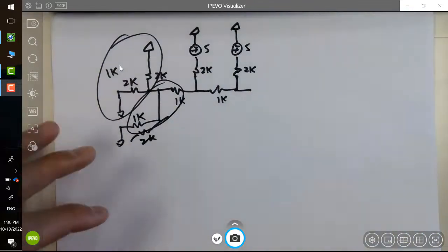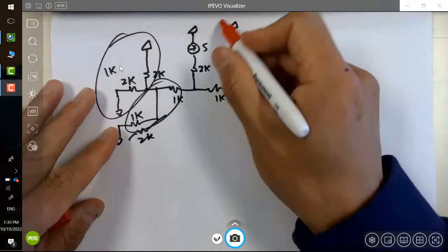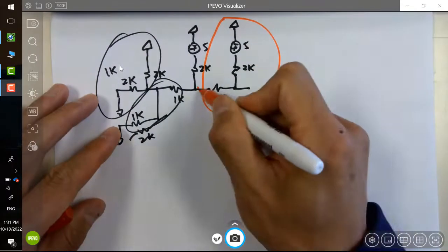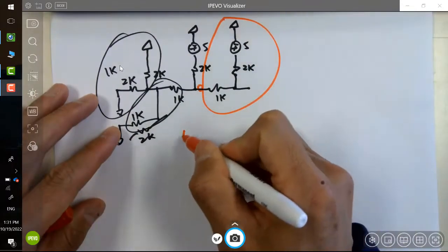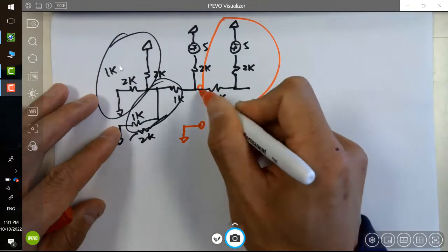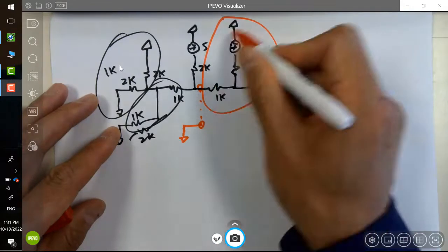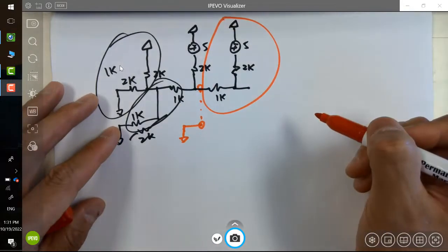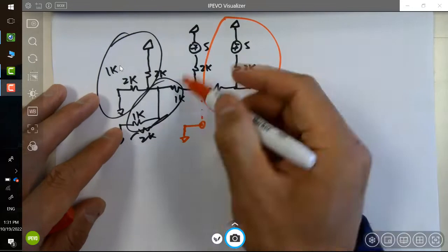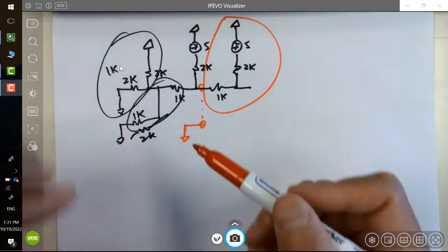Keep in mind that's critical because the shape of the circuit looks really odd. So you want to treat this one and ground here, I didn't draw it, so that's a network, and everything behind it is a load. Remove the load and then do a Thevenin here.